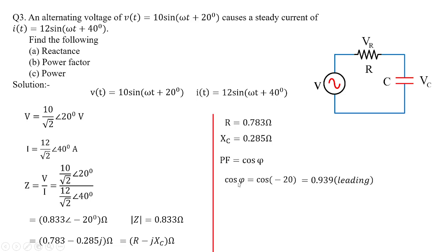And finally, power factor is also helpful to calculate that the power factor indicates that the capacitor and resistor connected in series to AC will make the current lead the voltage. So the power factor is leading here and the value of power is 56.34 watts.